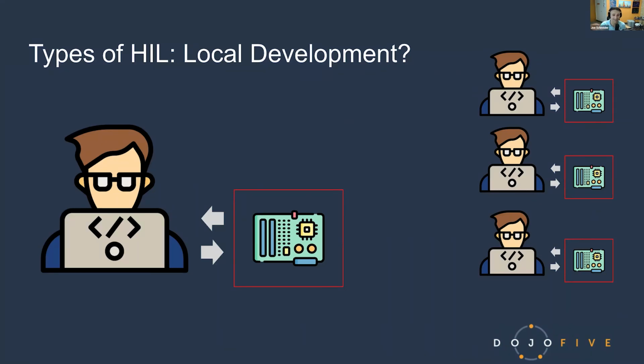It turned out they had a marginal issue at -40 on only some DDR chips falling out of the factory. So that's the type of thing you have to test on HIL, right? You're not going to be able to test that in a unit test, because it's a hardware related issue.